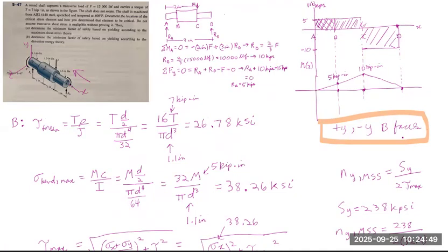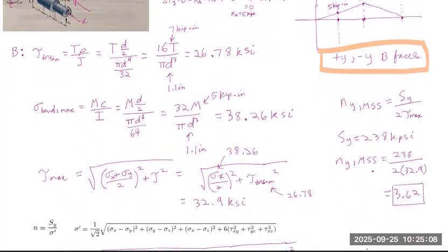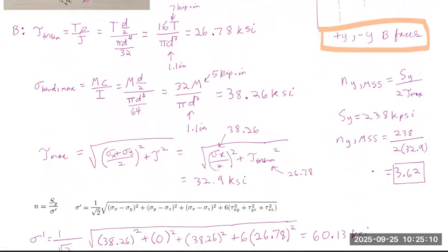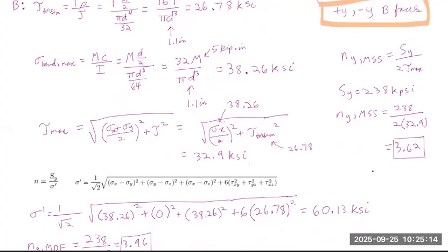The critical locations are areas with highest bending moment and shear stresses, as well as when the shaft is joined to another part. But ultimately, we identified different phases where they are subjected to stress, and we calculated the factor of safety for each phase, for each critical point.